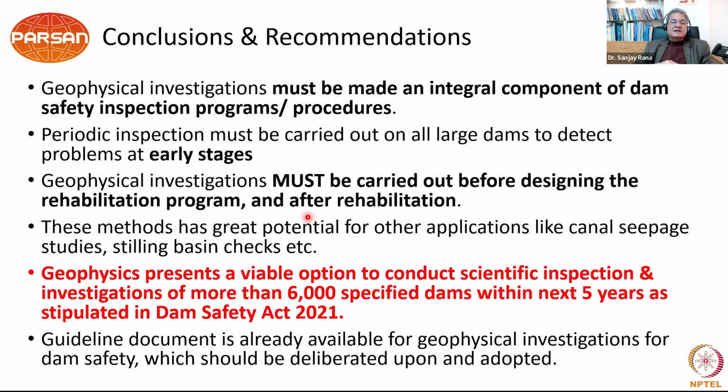So ultimately, the conclusions of this small session: geophysical investigations must be made an integral component of dam safety inspection programs and procedures. Periodic inspection must be carried out on all large dams to detect problems at early stages. Geophysical investigations must be carried out before designing the rehabilitation program and after rehabilitation. These methods have great potential for other applications like canal seepage studies, tank basin checks, etc. And geophysics presents a viable option to conduct scientific inspection and investigation of more than 6,000 specified dams within the next 5 years, as stipulated in the Dam Safety Act 2021.